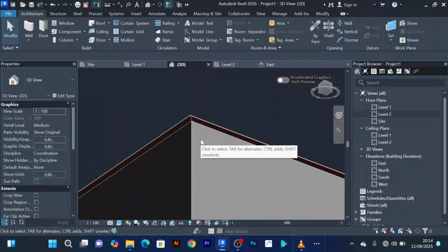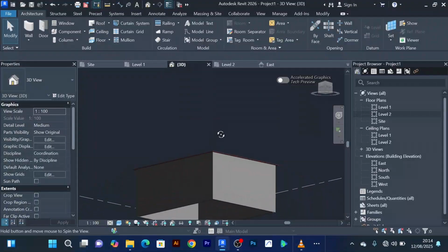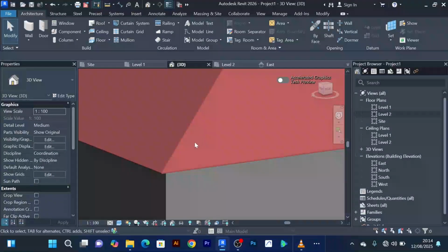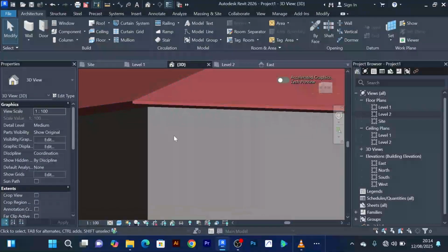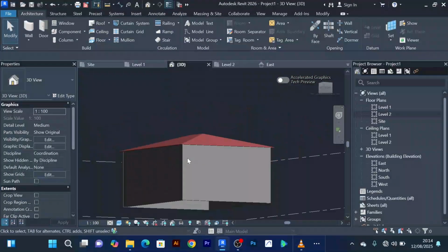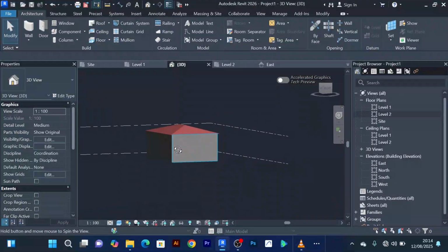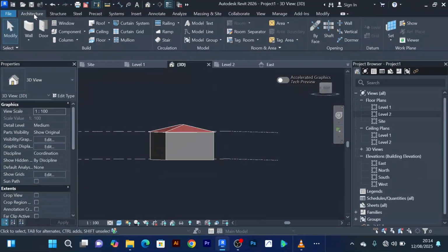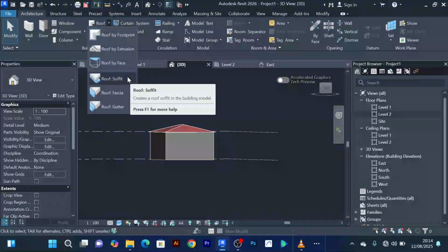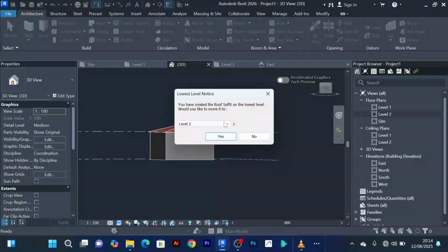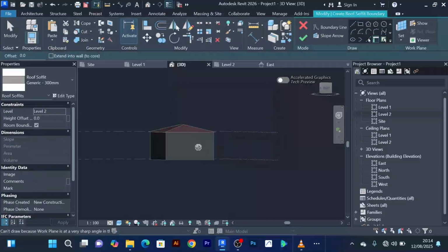And now after creating a roof like this, you can, of course, there's always what we call facer board, there's soffit, all those things you can create them here. Now to create those ones, you come back to architecture, you go to your roof. Now we can do, I think, soffit for now. Let's try soffit, and the level is of course 2.